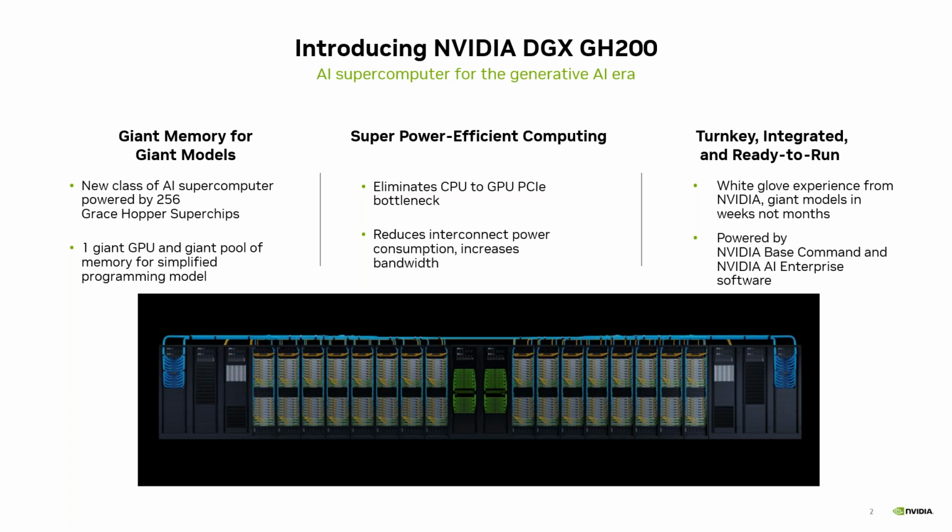Yeah, the 30 kilowatts does present challenges for air cooling. Certainly at 60 kilowatts per rack, liquid cooling is the obvious choice to try to remove a large percentage of the heat.